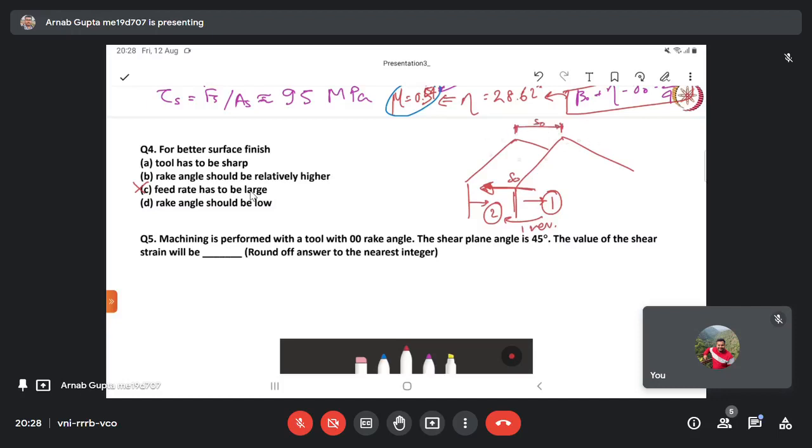So you can calculate this height here, if you take this section. The finished surface that you are getting is not a plane surface, rather it has undulations like this. This particular height you can quantify from these angles and this S0 value. You know this auxiliary cutting edge angle, you know this principal cutting edge angle, and you also know this S0. So from there you can calculate this HM. HM is a parameter by which you can evaluate the roughness of the surface.